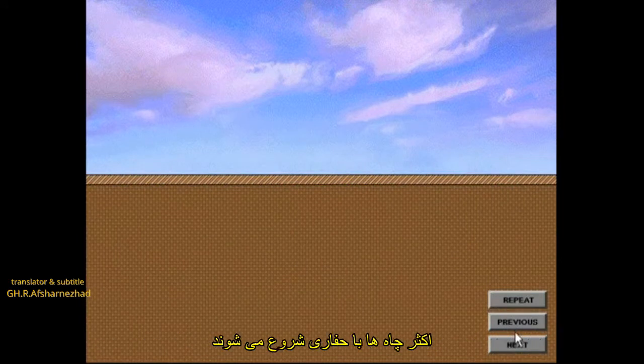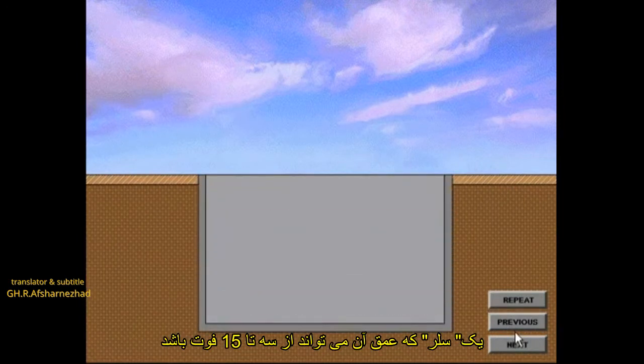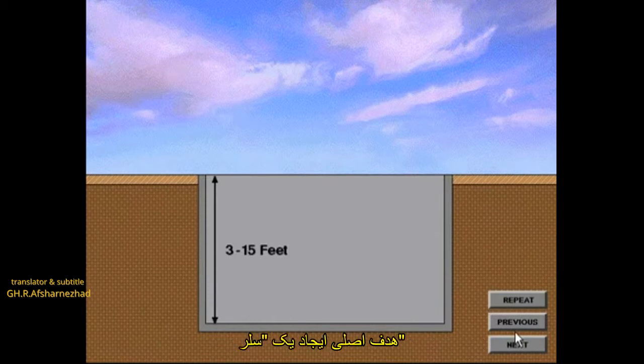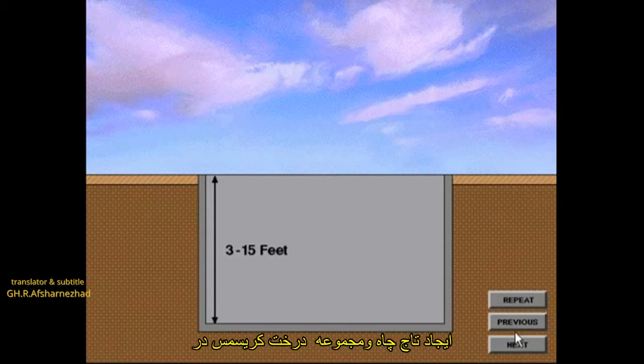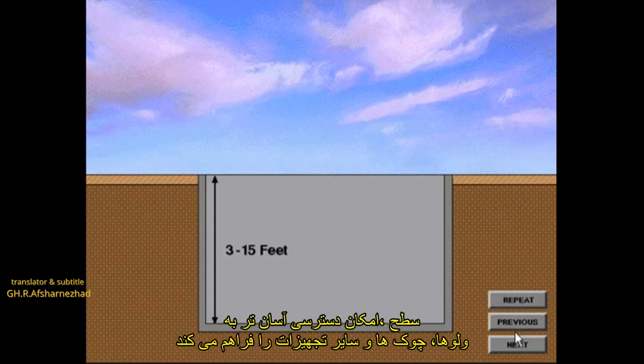On land, a majority of wells begin with digging a cellar, which can be from 3 to 15 feet in depth. The primary purpose of a cellar is to align the Christmas tree at relative ground level. Having the Christmas tree at relative ground level allows for easier access to the valves, chokes, and other equipment.